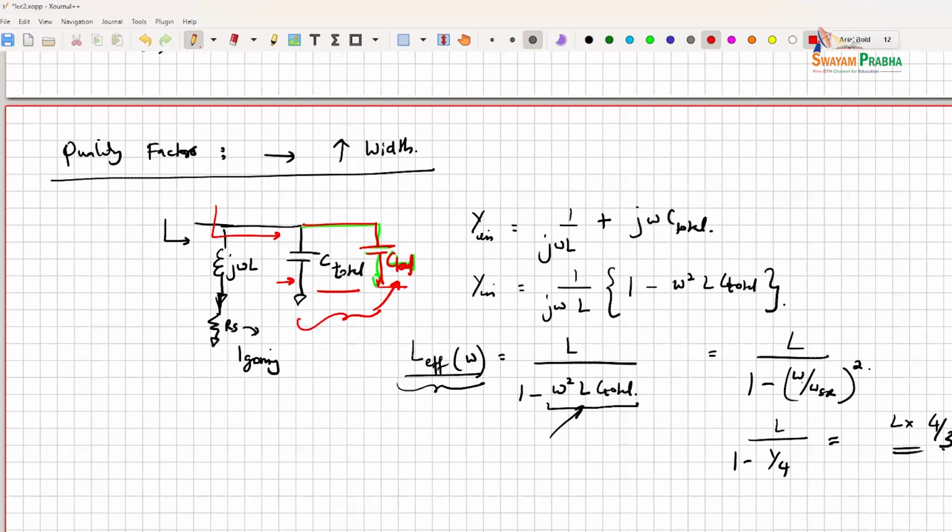And it is important to be aware of how you are using it, because let's say you decided to make your inductor very thin because you were trying to minimize this capacitance. You are actually doing a suboptimal design. Because what you could do is absorb it inside this and then use a wide metal layer for this inductance so that this resistance drops.